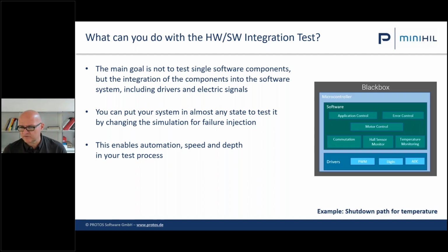Let's have a look at an example. So we regard the microcontroller as a black box. We test at the pins of the microcontroller. So the system under test in this case is a microcontroller with the complete software, application software, and the drivers. And let's have a look at this temperature shutdown example from before.